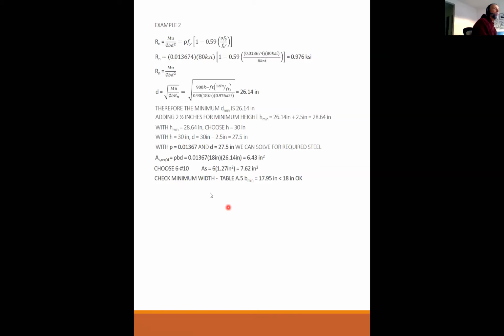Okay, all right. So this takes a little practice. Granted, I've been doing this a little bit longer, so I kind of have an idea what fits and what doesn't. But yeah, this takes a little practice. And again, if you find that no combination will possibly fit in the beam that you have, then you have to go to 2 rows. And if you have to go to 2 rows, you just go back up to here and start over from this point. You calculate what H is, and then from H you calculate what your D is, and then you come to a solution.